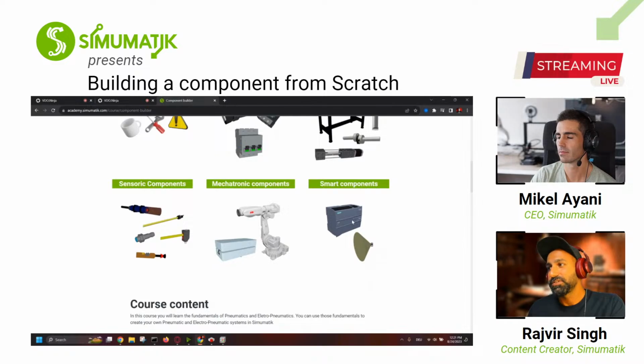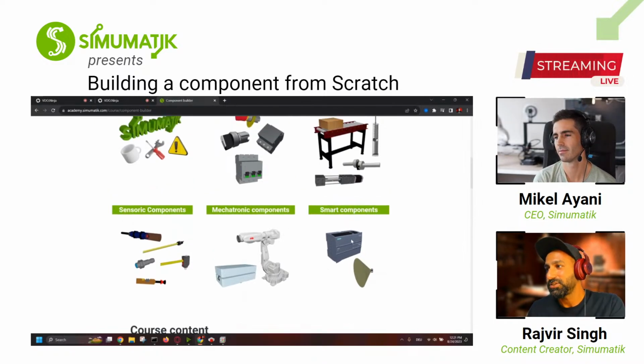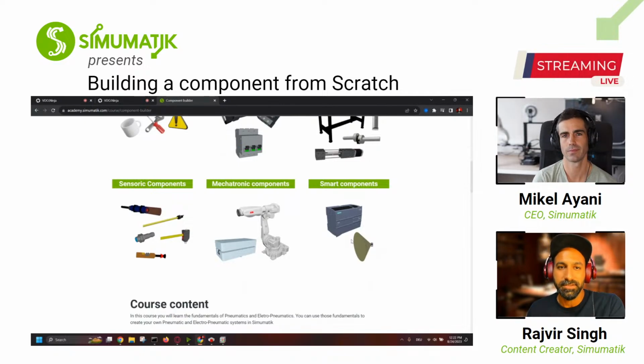Then the next category, which is very interesting, is smart components, because these components can interact with third-party devices using our communication drivers. So we have a lot of drivers in our gateway. For example, we have Siemens, we have OPC UA, Modbus. So imagine if you have a sensor and you want to read the signal from the sensor, not via voltage, but via Modbus. This you can do in the smart components category. So you can create your own smart sensors.